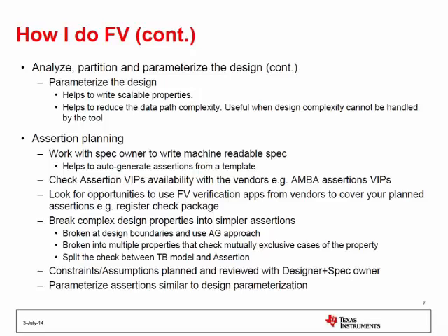And another important thing is it is not just the design, right? Assertions also you need to plan properly. You need to work with the spec owner to write a machine-readable spec. This is again a very critical point, because if I am doing combo logic or a control path, there are certain areas where you see this being repeatable or the functionality is similar.